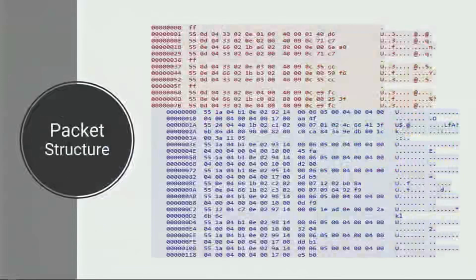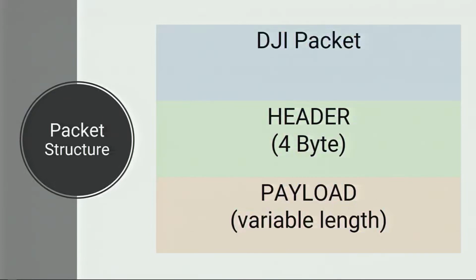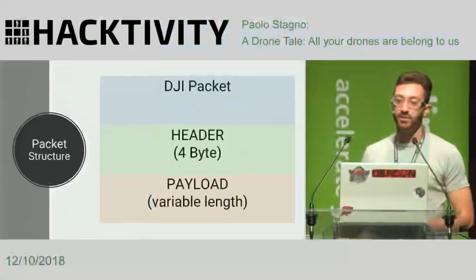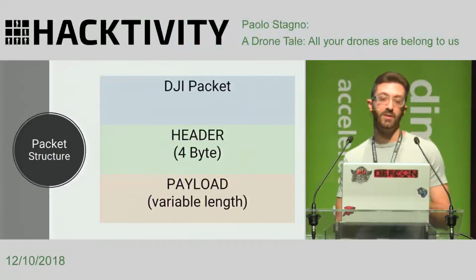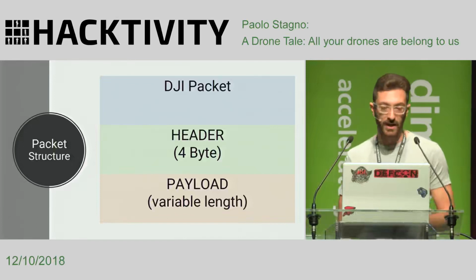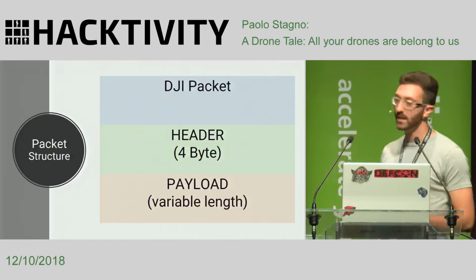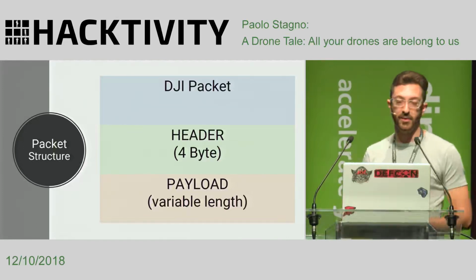And this is the communication flow between application and drone. I have filtered out all the UDP traffic, because UDP is used for video feedback between application and drone. DJI uses a custom TCP-based protocol for flight control. So I started some reverse engineering of the protocol, but fortunately, this protocol is very similar to the one used by previous models of the Phantom series. So some of the fields had already been identified by the community.